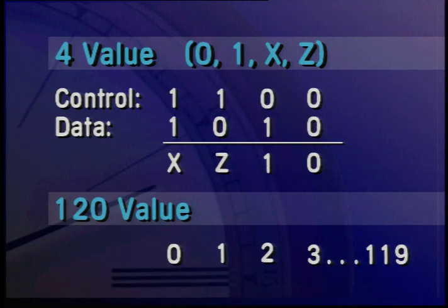These 2 models are built in, and whichever one is appropriate is used automatically by the simulator. VHDL, on the other hand, has a much more general model. The signal representation is not built in, but is user-definable, and in fact must be defined by the user. This has ended up with VHDL models typically settling on a few standards, a 9-value set, which is the most common, and a 46-value set.